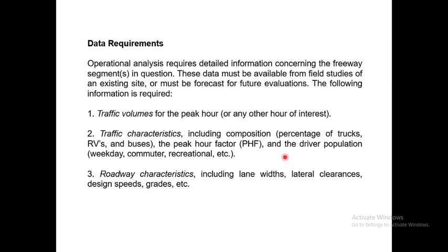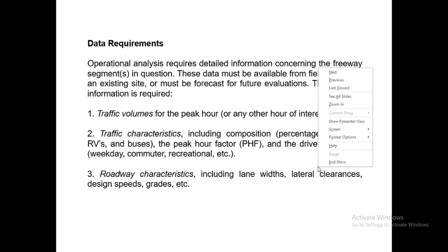So what data do we need for operational analysis? We need traffic volume, we need PHF. If you don't remember PHF, please refer to the previous session slides; it is the peak hour factor. Okay, because usually for analysis we talk about the peak hours. Because the peak hours are critical, we need a peak hour factor.